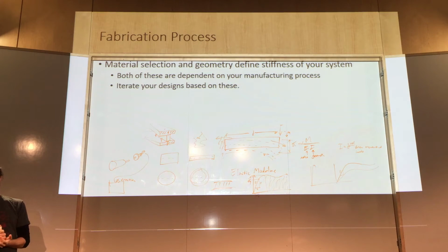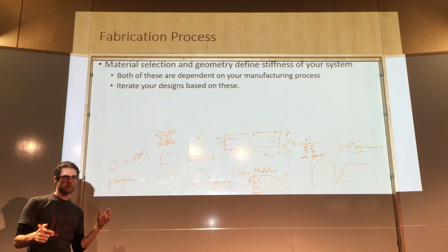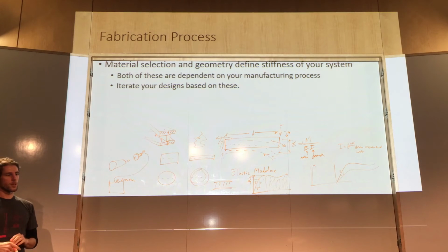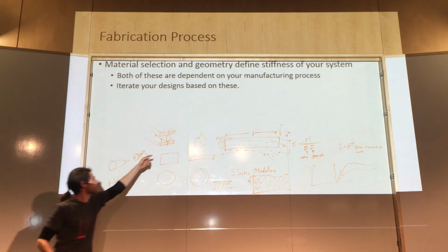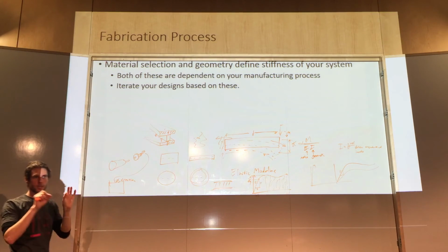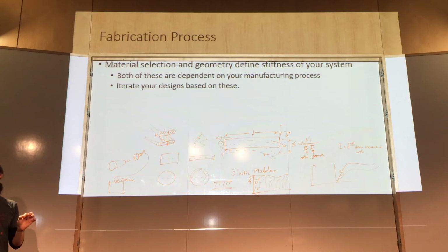So for instance, when I was building the last robot arm I was building before coming out here, we were looking at how we were going to make this thing. Originally, we did everything as milled aluminum, just these huge hunks of milled aluminum, which was really cool looking, but really, really expensive because I had to spend all that time machining away all of that material in order to get nice thin walls. There's a limit to how thin of a wall you can get when you're machining in general. So we ended up looking at a bunch of different manufacturing processes. And we wanted to do it potentially at volume also. So we were looking at casting, sheet metal, composites, all these different things, and they all have their trade-offs.